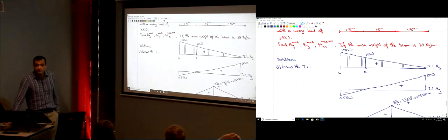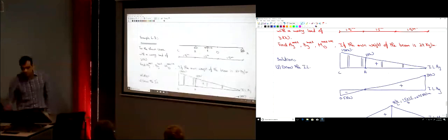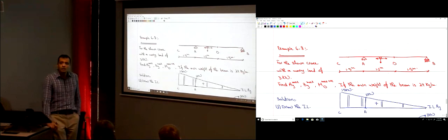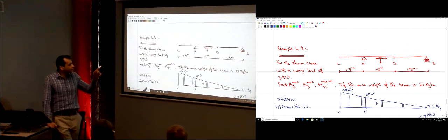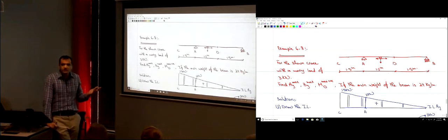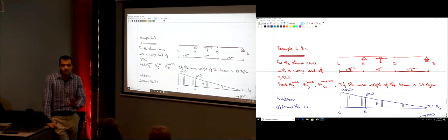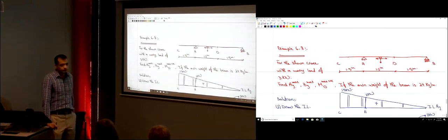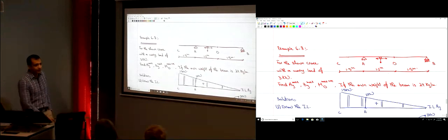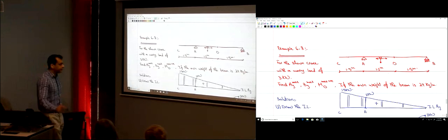If you had a support on the end, the support is at point A. I'm saying if you did have a support at C, would it have like a parabola shape in the moment? So you have a support at B and A and C. Yeah, correct. If you have 3 supports like this, it's going to be an indeterminate beam. And at this moment, we didn't learn how to calculate the influence line for an indeterminate beam. Hopefully, if we have time today, we're going to learn it. If not, then we're not going to learn it this semester, because it's not the scope anyway.